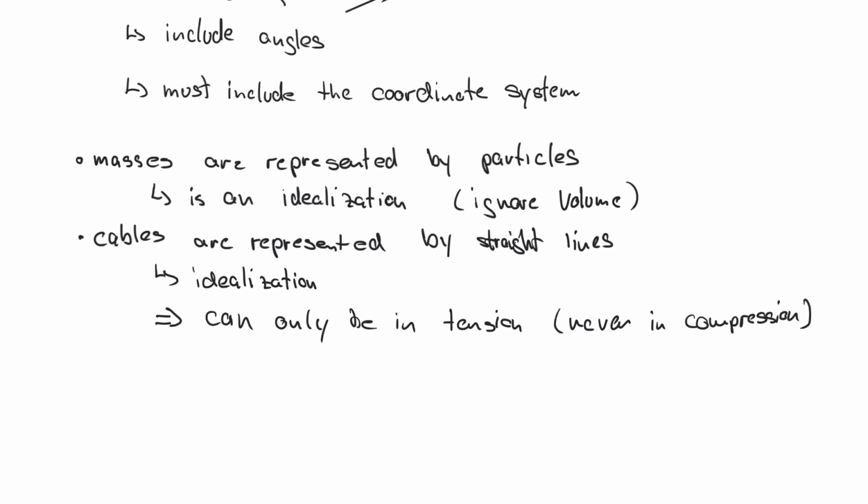And half of you are sitting there probably right now laughing about this statement because you think it's very clear, but you wouldn't believe how often this goes wrong. In fact, let me highlight this. So only tension is very important, because sometimes you may understand this physically and you would never answer this incorrectly in your real world examples, but when you run numbers you sometimes forget it, or students sometimes forget this. And I had a teaching assistant once who said that the students always come up with a compression cable.